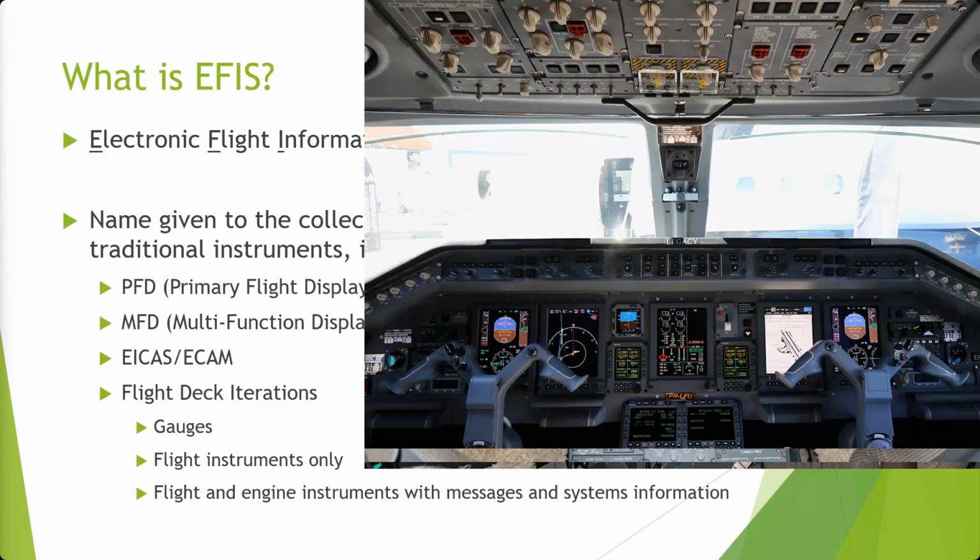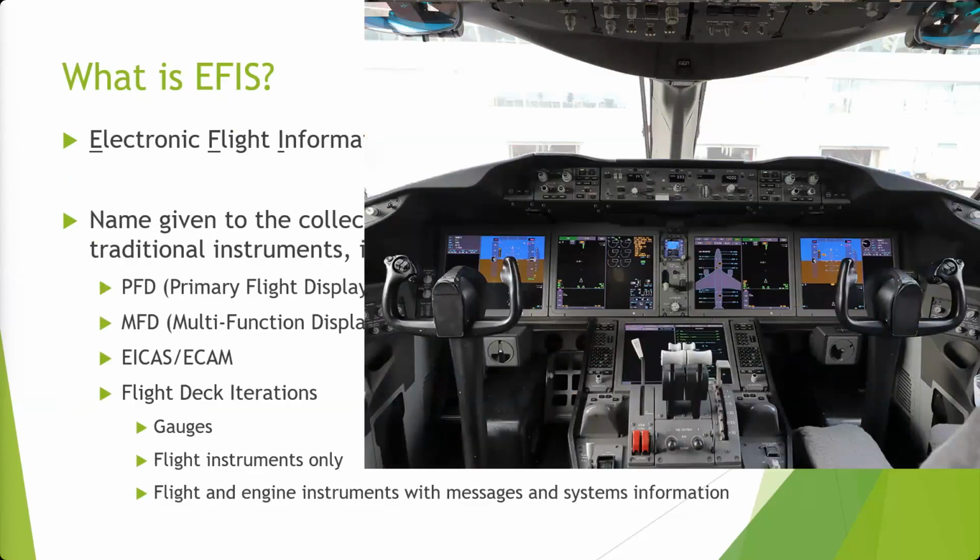And then in the middle here, we've got engine gauges, an area for messages, flap positions, landing gear positions, trims, and then the ability to pull up your secondary systems pages as well. And then these are your flight computers down here, or navigation program computers. It's an Embraer Legacy. That's a business jet. Sorry, I think I call it 190, 170, 190, and then the Legacy series are all interchangeable. I mean, the Legacy is the business jet version of the 170 family.